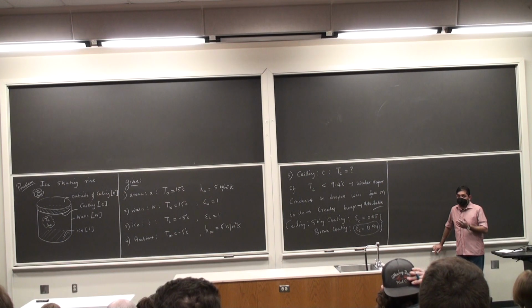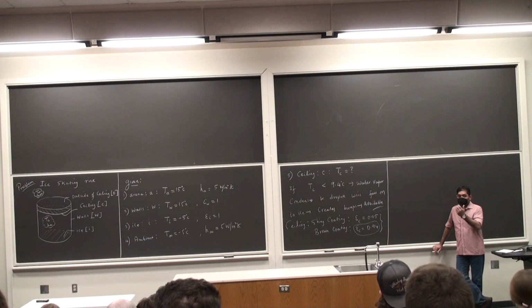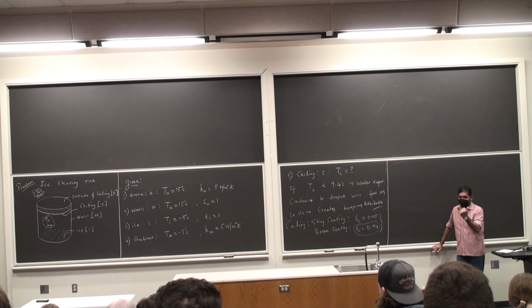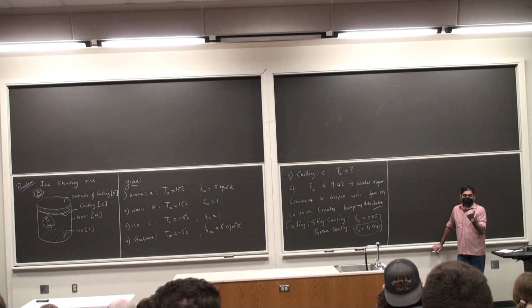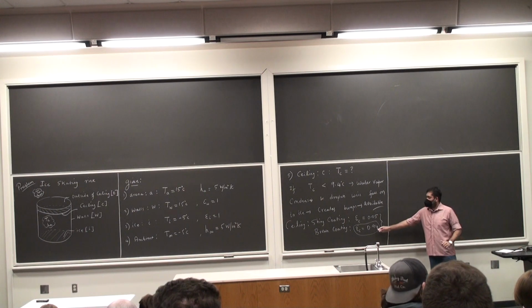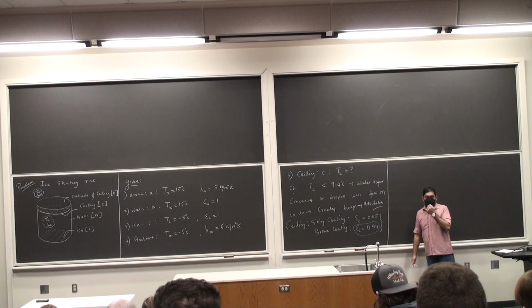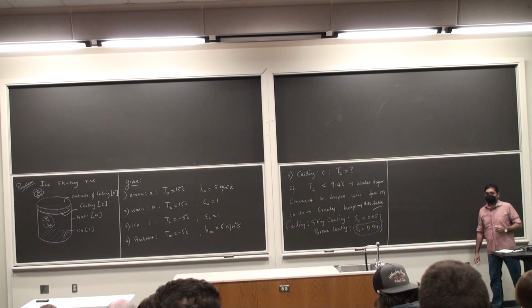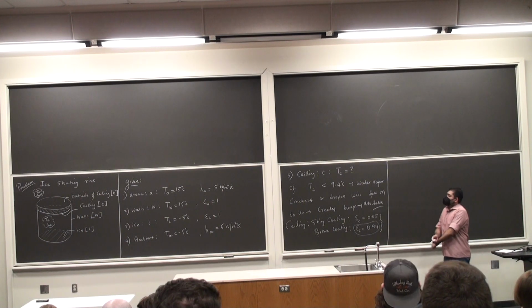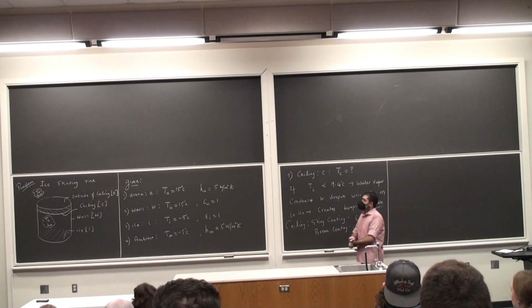It is because if the emissivity is very high, it means that there is more heat removed, more heat emitted by radiation, which means that it will leave the temperature of the ceiling to be lesser. So the suspicion is, perhaps this is not a good choice. It is not yet validated by any of the calculations that we have done, and our plan is to do all these calculations. Okay? Furthermore, you are given the following equations for the view factors.